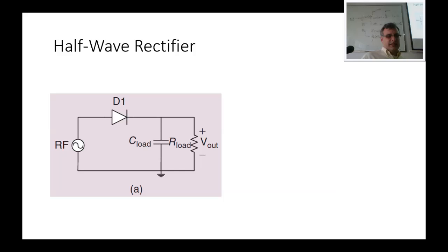Okay. So here, I'm going to finish up with just several different circuits that we use to harvest RF energy. This is the classic half-wave rectifier. It's the simplest possible circuit, and truthfully, if you understand how this circuit works, you pretty much understand how all of them work. Here's your load, your AC is coming in.